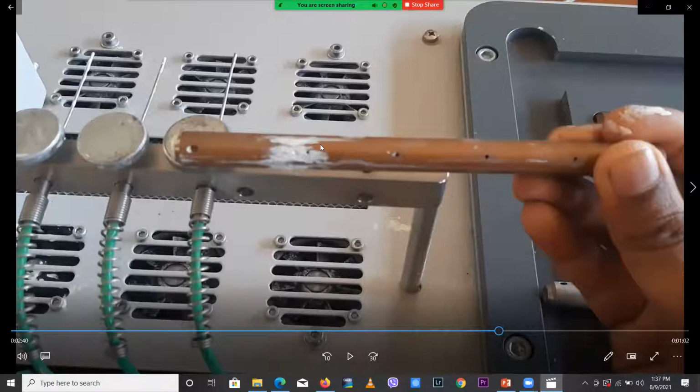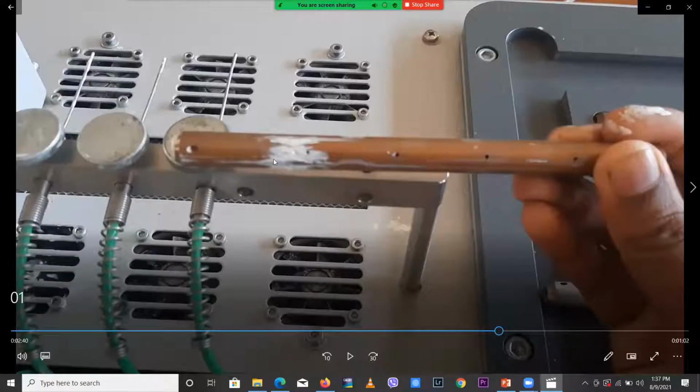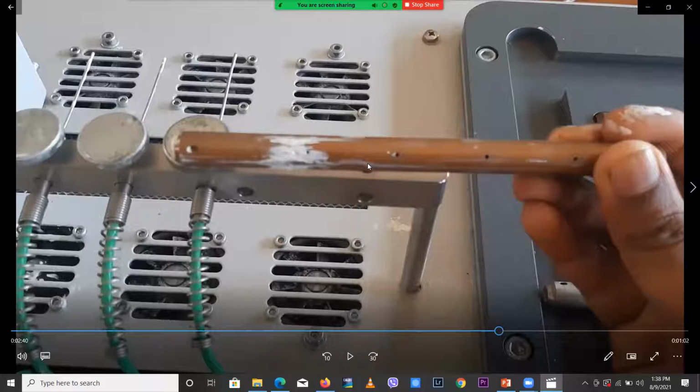That means there should be direct contact with the metal, inside of the rod. So we should sense the inside temperature of the rod, so we insert this thermoprobe inside, right? But we should make sure that if there are small holes or anything, there is no air. We should make sure there is no air.